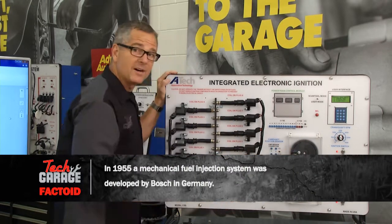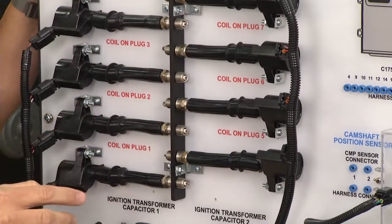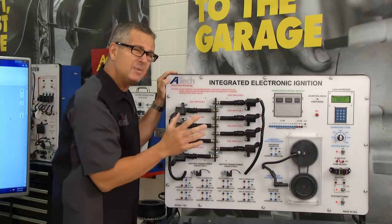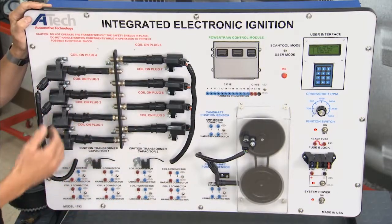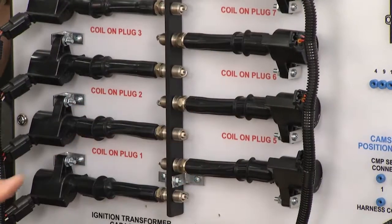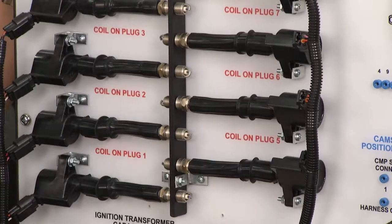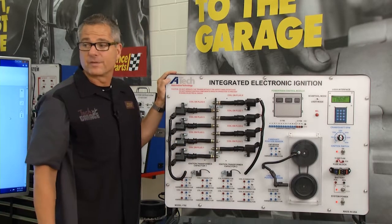Now what Brian found is actually a coil on 5. Number 5's not firing. You can see we disabled coil 5 on this one. So we probably suspect it's not a cam or crank sensor because the rest of them are firing. So if you have one, what we have to do over at the car now is he's got to look at the primary and secondary. We need the input on the primary, and we can do some secondary measurements to isolate what's going on with that system. Brian, how's it coming over there?